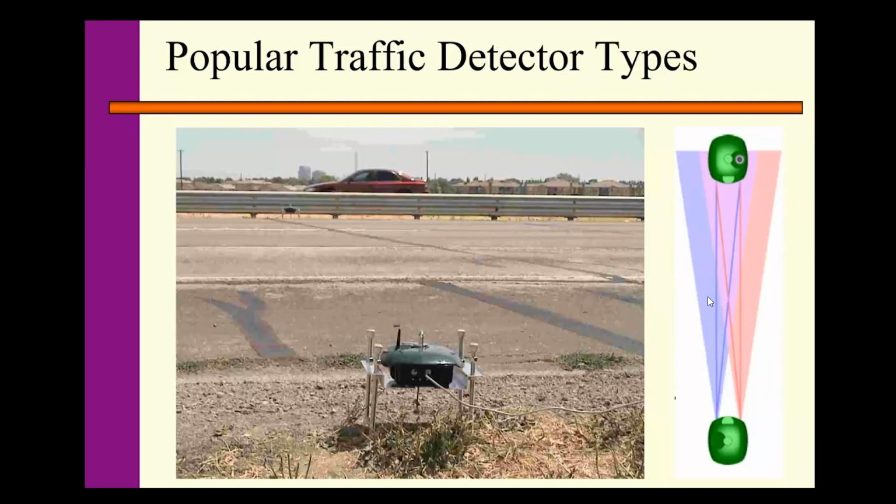The two parallel sensors can tell us how many axles pass through this particular point. Based on a certain algorithm, we will know how many vehicles pass through this designated point. And then we can estimate the load of the vehicles and the impact on the pavement.